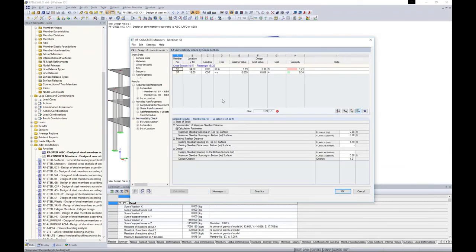This is more so in table format. Looks like we're a little bit overstressed, or not overstressed, but our limiting crack spacing for our torsional reinforcement is exceeding the capacity here. Well, this is a good example of a live webinar. It was passing before, but it looks like now we aren't passing, so maybe we'd want to go back and address some of the spacings for our longitudinal and shear reinforcement to meet those code standards.